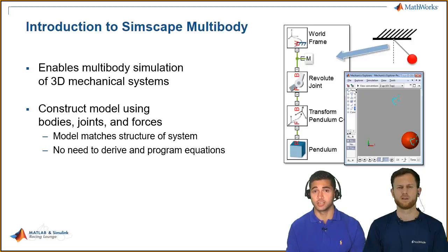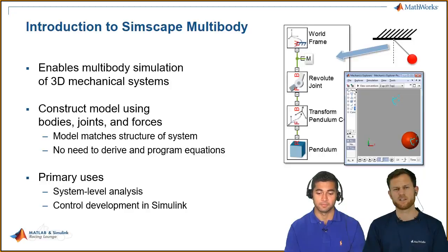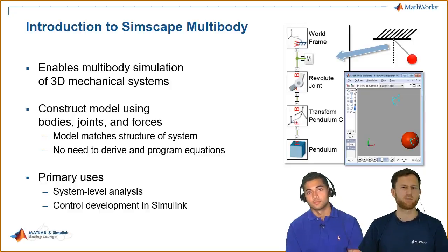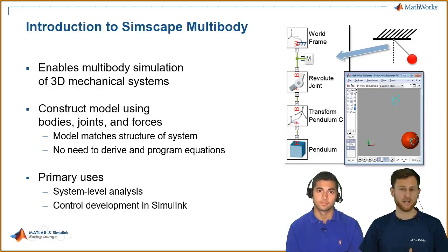Okay. And just like other Simscape products, there's no need to derive or program equations. All of these are taken care of by Simscape. Just to summarize for you guys, basically what you're modeling in Simscape Multibody is actual 3D components. You're modeling the geometry, you're modeling the interfaces between them. So for example, for a pendulum, it's a certain rotary joint or rotational joint. And basically, Ed pointed it out already, you're getting for free, without extra modeling effort, a 3D visualization.